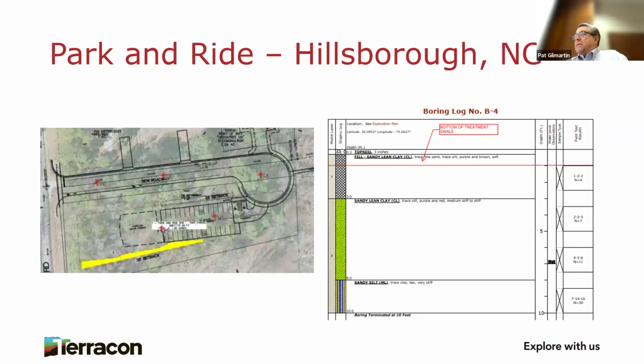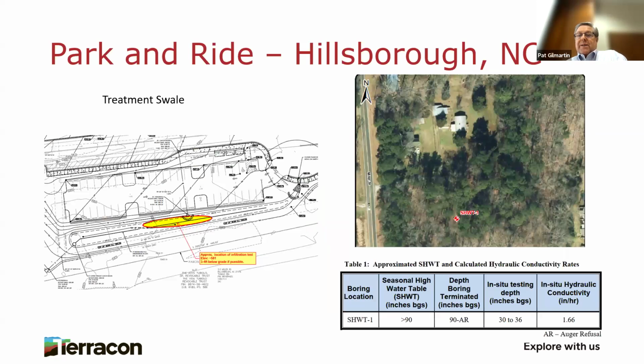Smaller project, small runoff, treatment swale, probably one of the only treatment swales that I've been involved with. So then the site civil engineer requested some input for the design of that treatment swale, including an infiltration test. Terracon, we don't locally have licensed soil scientists in-house. There's some good ones that we work with in the region. We subcontracted one of those, and they evaluated the depth of the seasonal high water table and tested the infiltration rate as requested.